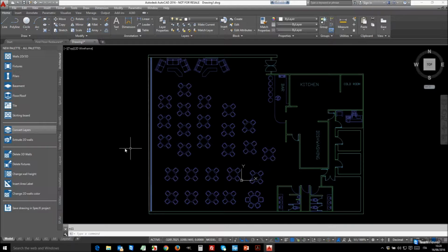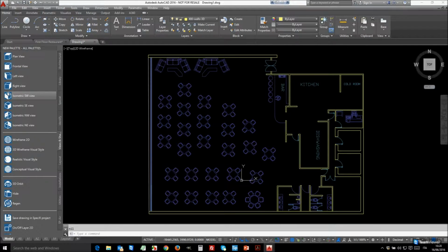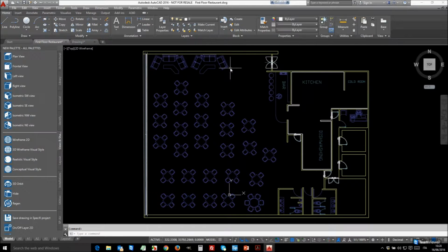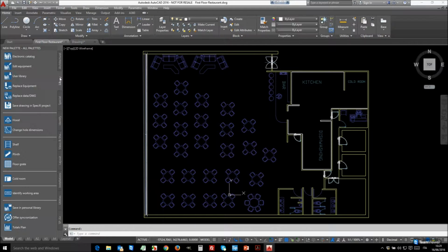In Specify, in our palette we have a few commands. One of these is Convert Layer, which permits me to select a wall, for example, and link it directly with our Specify bidimensional walls. It changes the color of our walls completely, and now I can extrude the bidimensional walls into 3D. We have a command that permits choosing the height of the roof. Supposing 3,500, and enter. Okay, and you can see the result. So we already have all our three-dimensional walls.